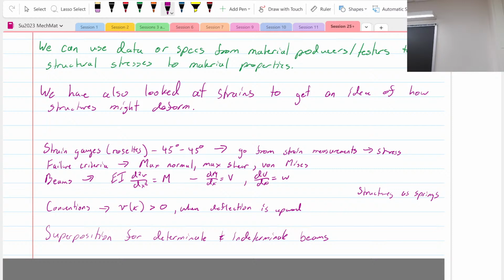Yeah, it starts leaning. That's another problem, right? It's interesting, at least in a normal compression type way, when you make it thicker it becomes more squishy. The spring constant goes down. As you make a beam thicker, as you make it larger in its height or thickness, and you go across, that of course will make it stiffer, because we think about what's happening at the end usually.